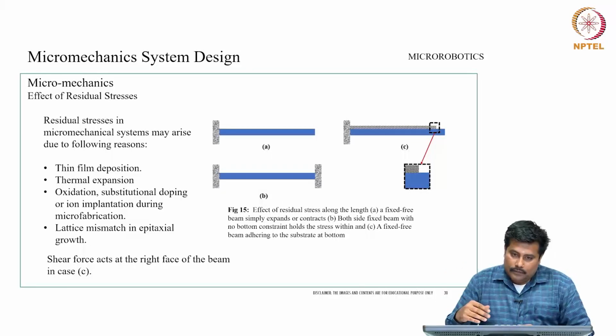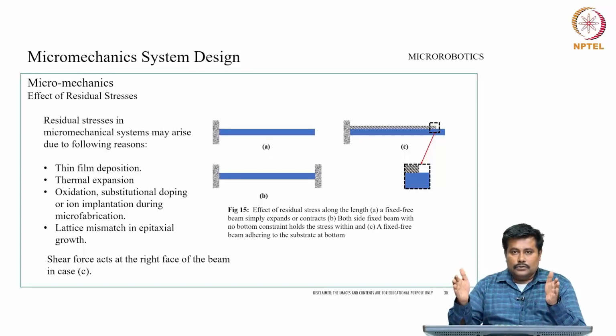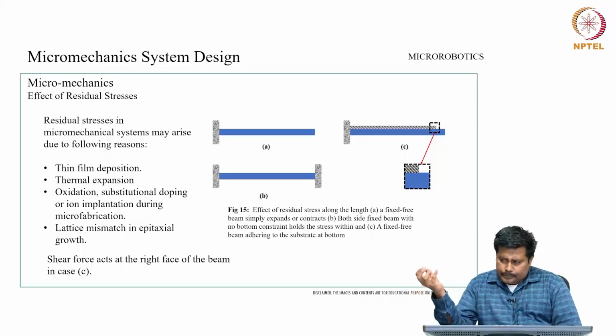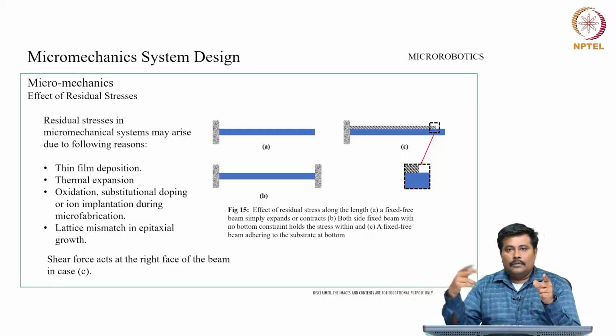In fact, we had also performed certain experiments with shape memory alloy springs. What we have done is we have used a shape memory alloy spring, connected with two hooks, and by using a programmed power supply we supply joule heating to it in a programmed fashion, and a load is tied to this particular spring. So, the spring will expand because of the load, and when we supply heat to it, it comes back to its original state.